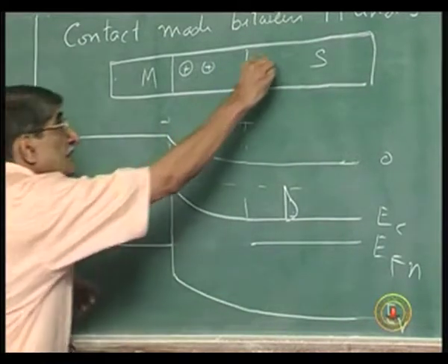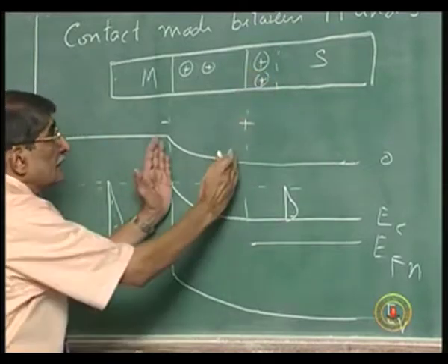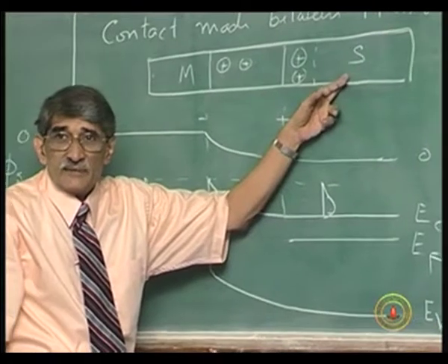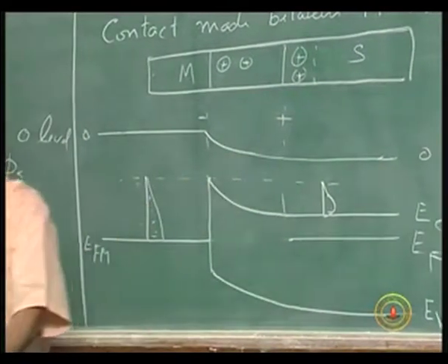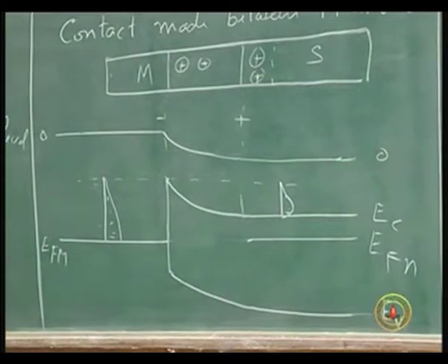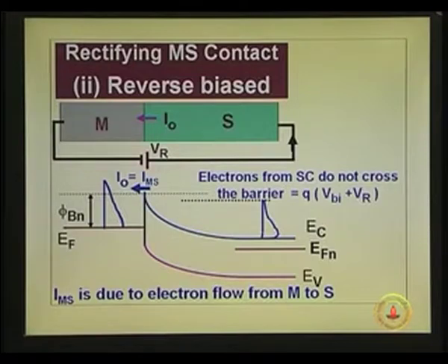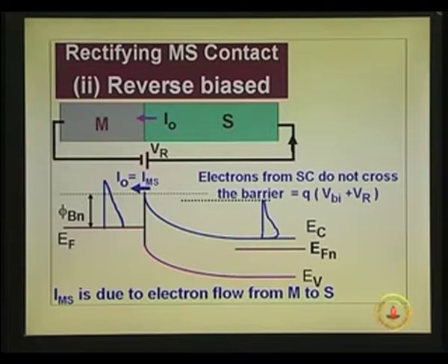So this depletion layer will widen, uncovering extra charges, and what happens to the potential at this point? The energy level at this point goes down further, because you have removed more electrons from there, so the energy of those levels will go down further. That is why you get the entire thing shifted down. You can just watch carefully, that was up there, going down. So this whole curve now comes down.